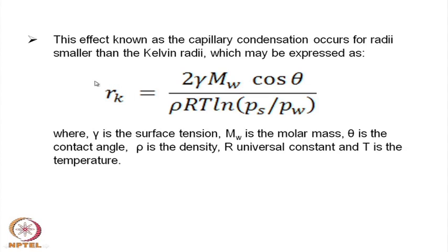If this is too large or too small, then condensation will not take place and the material cannot be used as a sensor. So, if you have an insulating material and the pore structure can be controlled in such a manner that the condensation takes place, you have a variation in capacitance, and by measuring the variation in capacitance it can be related to the relative humidity of the environment. So, this is how one can also use ceramic materials for the sensing of moisture, one kind of gas, in that sense.